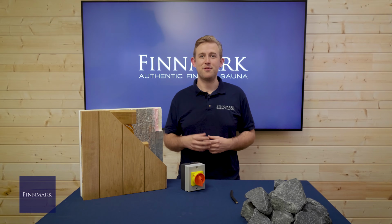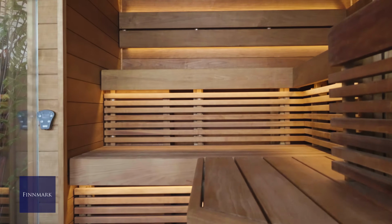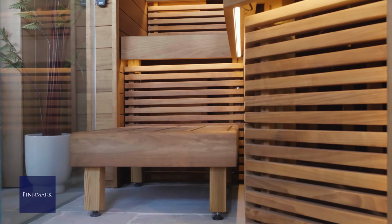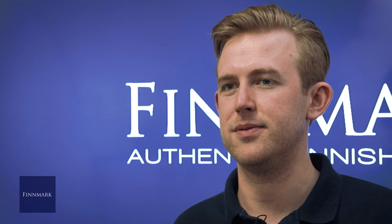We always suggest going for a tiled or porcelain tiled floor with a high anti-slip rating. In commercial applications, this should be as high as R13, though in domestic settings, the sauna will likely form part of a wet room environment, and therefore R11 or higher is acceptable.